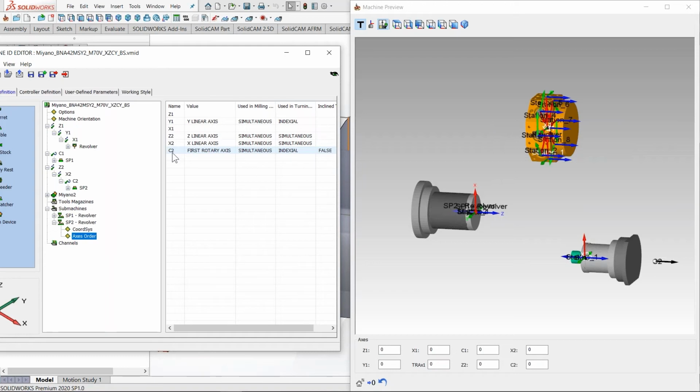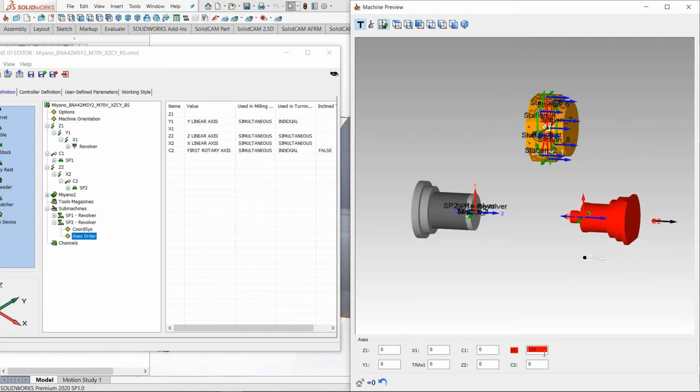When I got this machine to work on the post-processor, my question was, okay, which one is the master one? Does the sub spindle need to go and align its position with the main spindle and then work with the upper turret, or must the upper turret go a little bit lower, and then my sub spindle should work on that tool? In the end, I realized the machine can support both of these, but it can also support superimposition. So I'll try to define the minimum of the things.